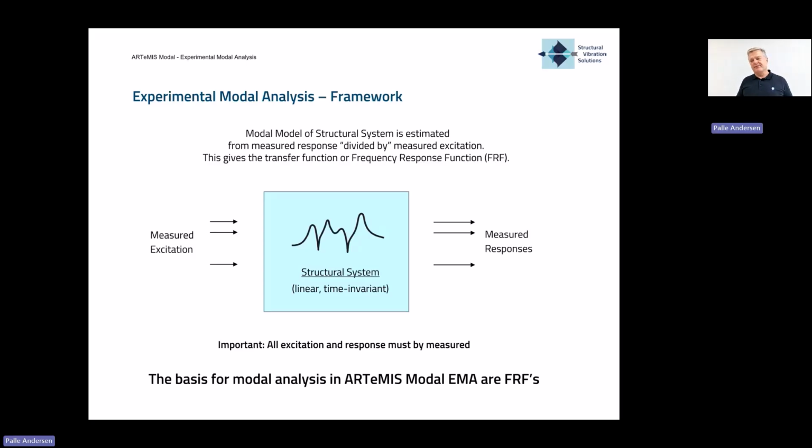There will be some unknown input forces mixed together with the known measured. And this is not good. It will be terrible for the results that we get out, if we have this kind of mix. So it's really important that the structure is isolated in some way, so that the excitations that you supply are the ones that actually are being measured, all of them, and used.